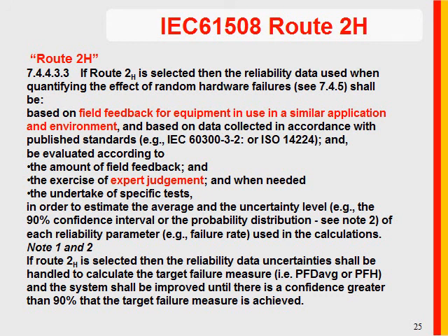One of the things is that we went through a pressure relief valve assessment at a site here in the U.S. We came to the conclusion that we could have concluded an average probability of failure for a relief valve, but in reality there was a strong indication that the specific location in the plant was a contributor to the probability of failure of that relief valve.